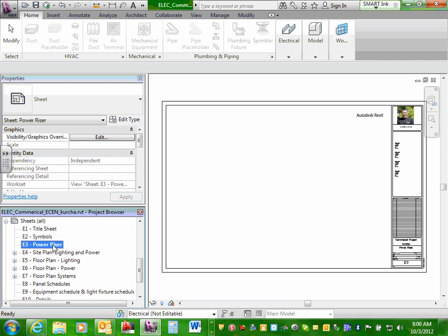Option two, take views of the electrical equipment, actual physical 2D views of the panel. I'll show you how to take a view. Here's the panel sitting here. I stand right here and take a view of the panel. And then all the panels in the building, you drop them in here, and then you tie them with a detail line. Draft them right in here.